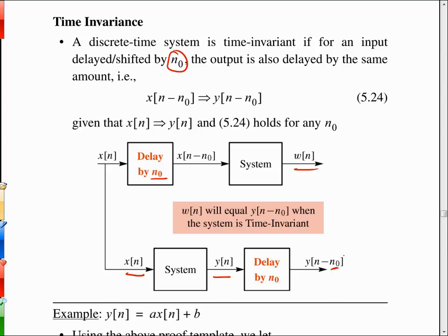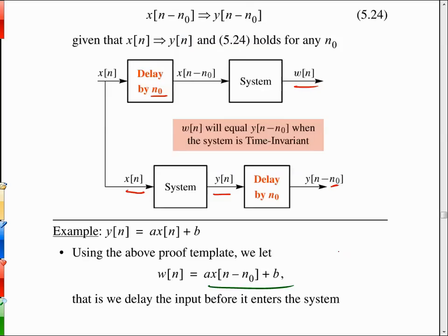So electronic circuits age over time. If you're a digital person, you'd say, but digits are always zeros and ones. They never change. But you've got to have a lot of digits to make an analog waveform, so there's some inefficiencies in there. And then there's also the analog interface circuits that'll change. But time invariance is not something where you have to consider it over decades of time. Time invariance to be good just has to be over the interval that you're interested in processing the signals. So maybe it does change over a period of a year or more, but over a few milliseconds, it looks time invariant. So that's another aspect of the time invariance idea.